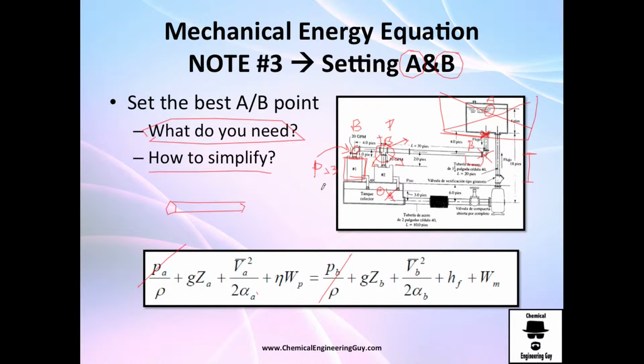The important part right here, guys, is once again, be sure of what balance you do. For example, you have this pump right here. There is a very important topic in pumping, which is cavitation, and it is the minimum pressure you need at the suction in order for the fluid to maintain its liquid form. If it turns to gas or vaporizes, it will destroy the pump and it will be a catastrophe.